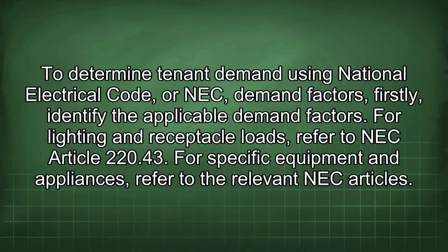To determine tenant demand using National Electrical Code, or NEC, demand factors. Firstly, identify the applicable demand factors. For lighting and receptacle loads, refer to NEC Article 220.43. For specific equipment and appliances, refer to the relevant NEC articles.